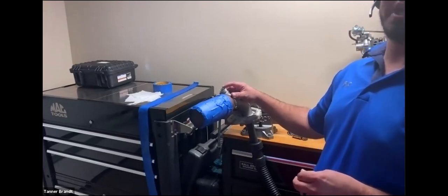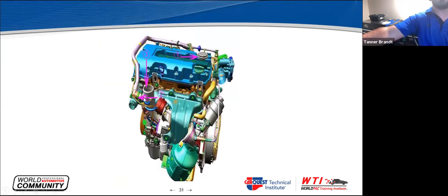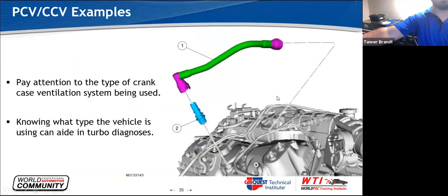When we start putting vacuum here, we are then in return putting vacuum on this right here, which in return is going to suck up this little check valve, because now you're going to have, as we saw, 9 psi of vacuum that's going to all of a sudden end up on this tube pulling on that rubber check valve.